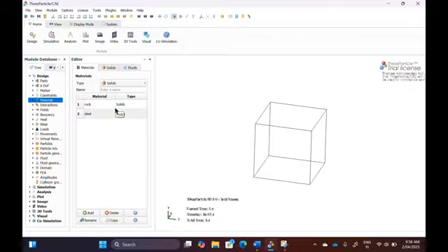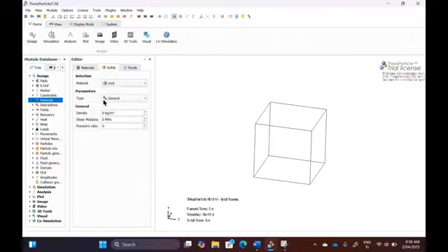Again, if you double click it, you can change some details on that. Now we have set a name, but not yet a density or anything more. Those three are not optional. Those three need to be set. Density: let's say our rock should have 2,500 kilograms per cubic meter. It's the solid density of our sphere. Remember, our solid density probably is not the same as the real physical one, because we have a sphere and not a real rock structure. Probably we need to fine-tune that, but let's keep with that.